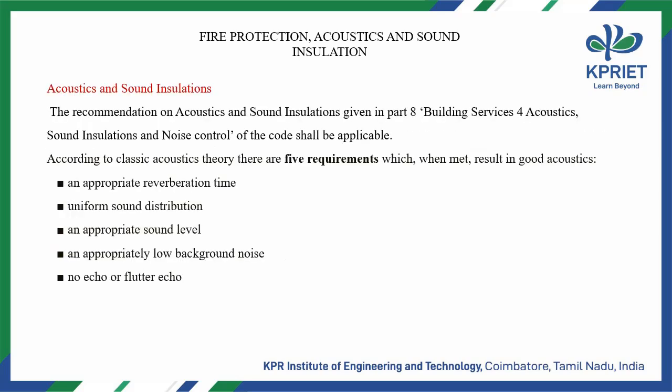Acoustics and sound insulation. The recommendations on acoustics and sound insulation given in Part 8 Building Services, Acoustics, Sound Insulation, and Noise Control of the Code shall be applicable. According to classic acoustics theory, there are 5 requirements which, when met, result in good acoustics. An appropriate reverberation time. Uniform sound distribution. An appropriate sound level. An appropriately low background noise. No echo or flutter echo.